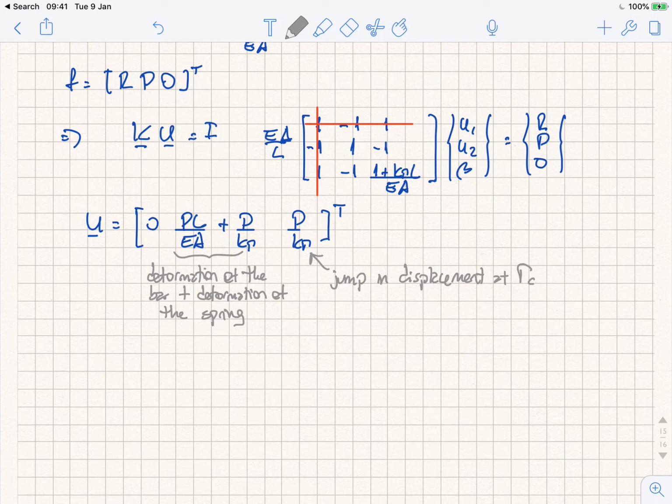So in other words, right now we are solving this problem with 3 degrees of freedom, right? But if I really want two independent fields to the left and to the right of the bar, 3 degrees of freedom is not enough. I need 4, right? So if you were to solve this with the standard FEM, you need 2 degrees of freedom to represent the displacement on the left component and 2 degrees of freedom on the right. You follow me? And now the formulation that I'm using has only 3. So kinematically, it is not possible to recover the general solution for which the slope changes at either side of the bar. You have a question?